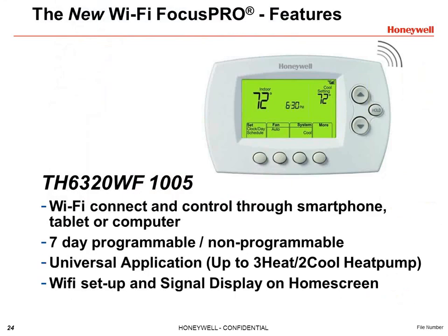So I'm going to start with the Wi-Fi thermostat line. And this is a standard 6000 series thermostat from Honeywell. Most contractors are going to be familiar with this thermostat. There's millions of them sold. The only thing that changes here is that now it's able to be connected to a Wi-Fi router. So you hook it up as a standard 5-wire thermostat. It's going to talk to the Wi-Fi router, and the homeowner or business owner would be able to get control of this thermostat via a smartphone or a tablet or a laptop, whatever it is.